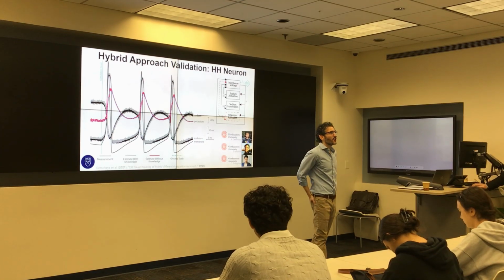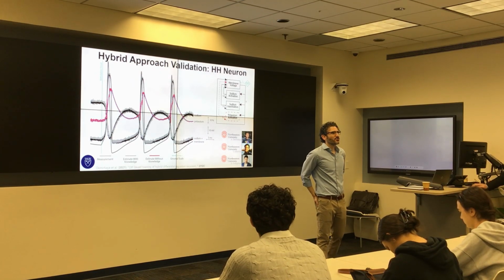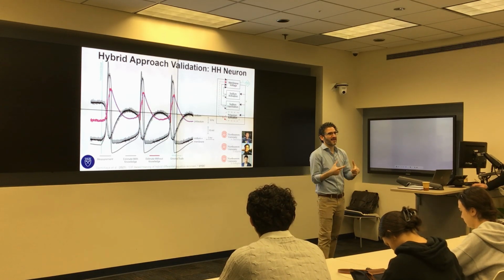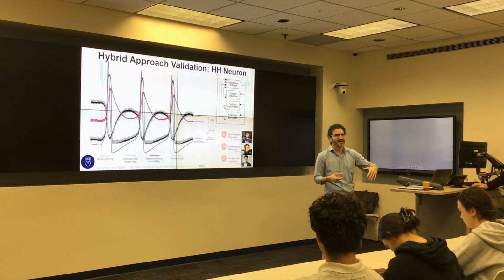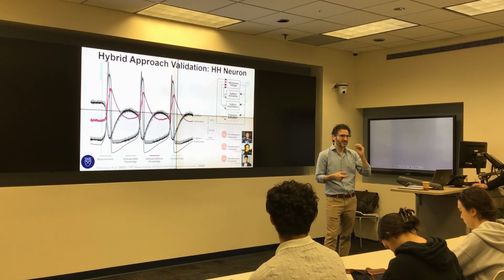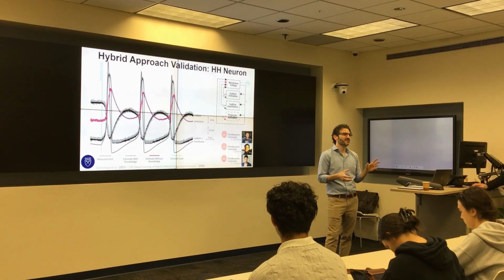How nonlinear? So we try very hard to keep the measurement model linear. We will rewrite our differential equations so that the left-hand side is expressed in something that's almost exactly what we measure, to get rid of those nonlinearities.